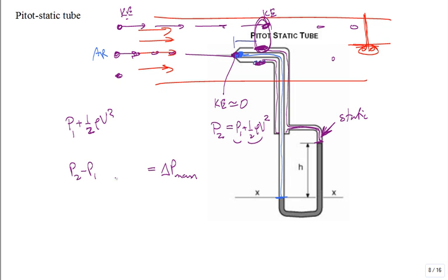And the difference in the pressure in the tip and the sides is 1/2 rho v squared, which is the velocity pressure. Or some people will call this not the velocity pressure, the dynamic pressure. I prefer the velocity pressure because it's coming from the fluid having non-zero speed. But I think this book and a lot of books call it the dynamic pressure.